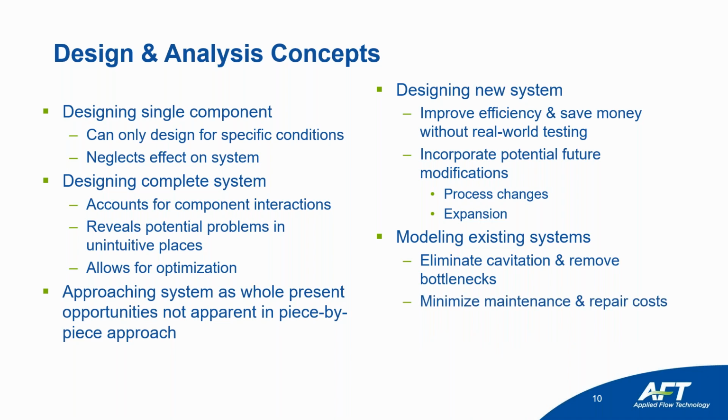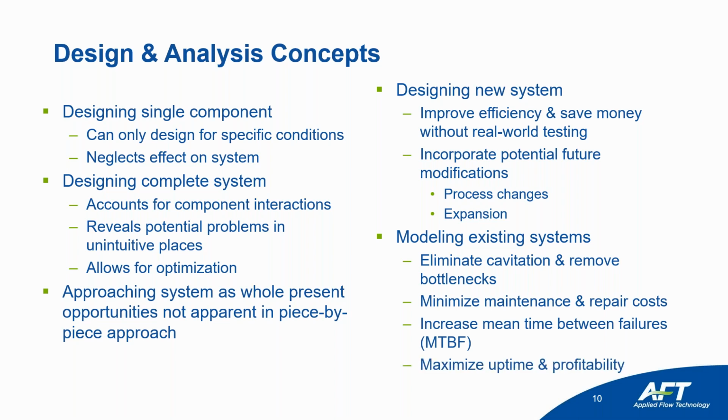How would you do that? Well, just by examining where your pumps are operating on the curves. And so if your pumps are operating far from their best efficiency points, then that's going to be a big indicator that you're probably going to be dealing with lots of pump repair issues. It can also help you increase the amount of time between failures, maximize uptime and profitability, and of course, efficiency.